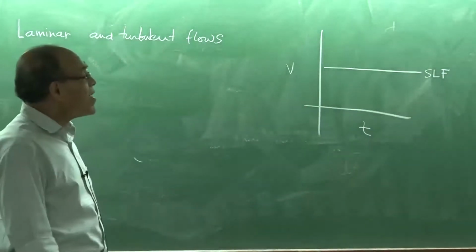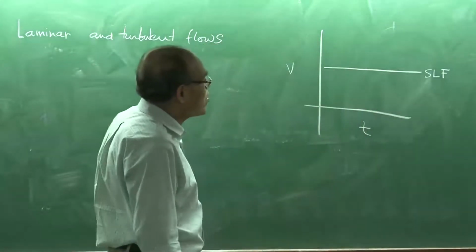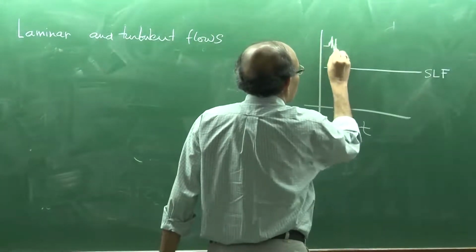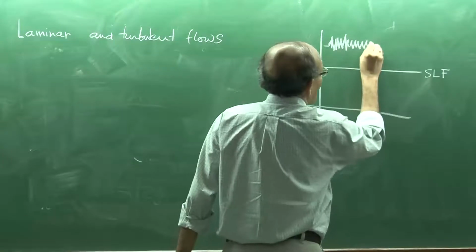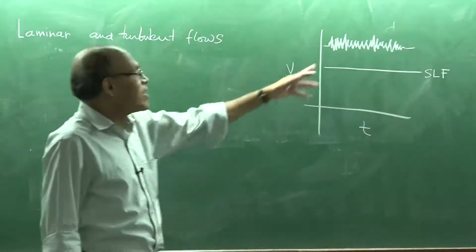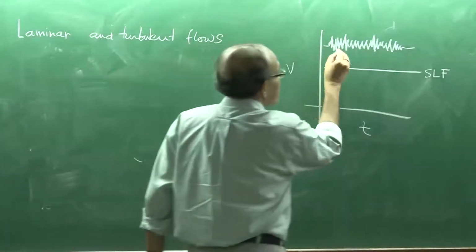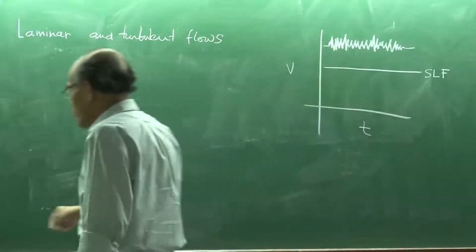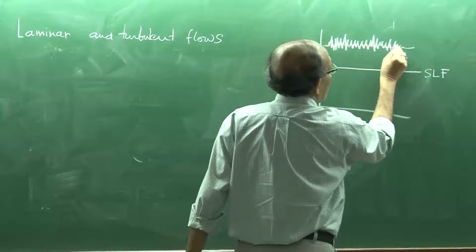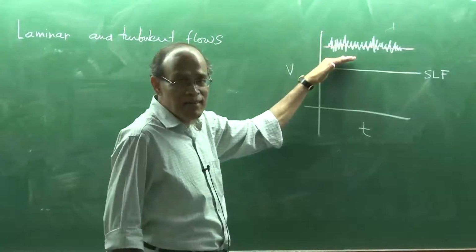On the other hand, if I want to represent the steady turbulent flow also in the same way, we will get a high frequency fluctuation, even if the flow is steady. That is the kind of signal that the probe is going to give me once it is focused into a region of the flow. Nonetheless, this can be split, and I can say that this is the mean component of the flow. So there is a steady feature, and the fluctuations are there.